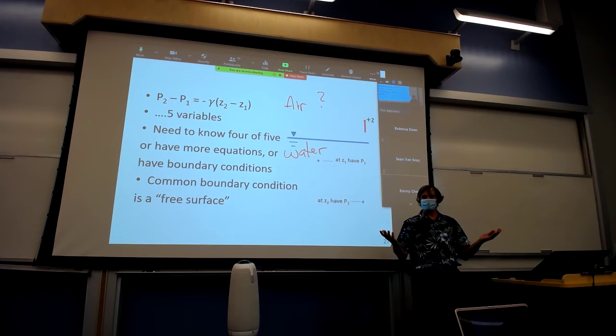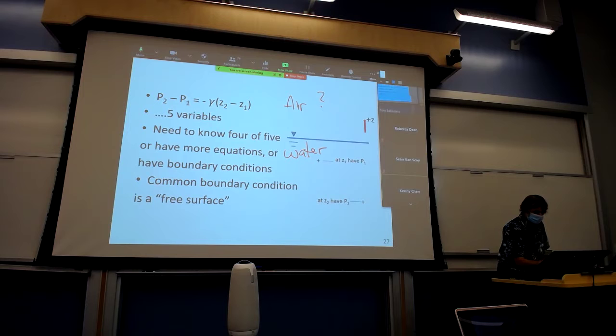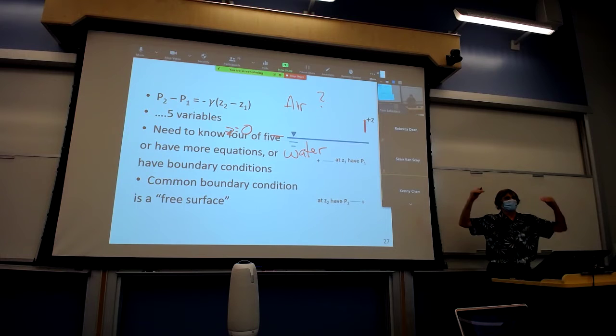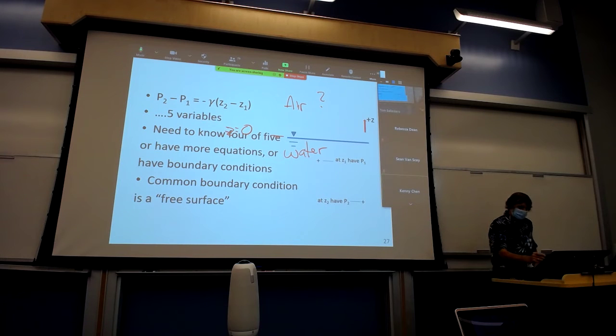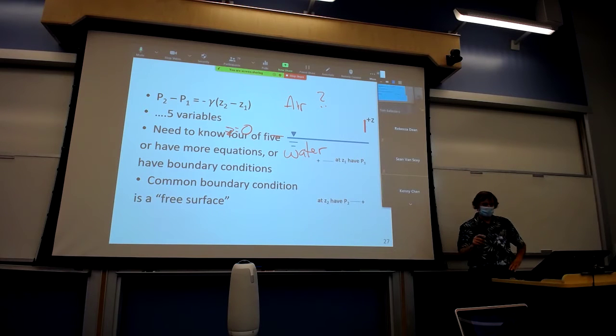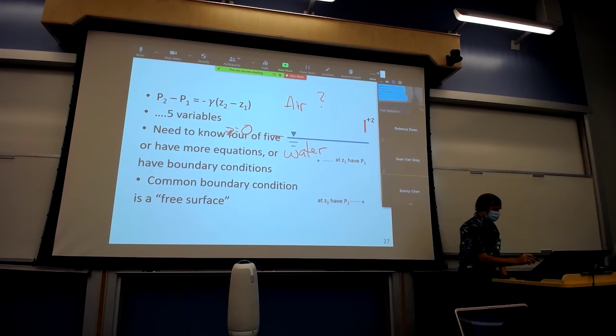What do we set all of our local gauges to? 0. 0 psi, 0 Newton per meter squared, 0 Pascal. That's the local datum. Just like we can say that Z is equal to 0 right at the fluid surface interface. So what you know is when you have atmospheric pressure operating on top of a fluid surface, that's known as a free surface.